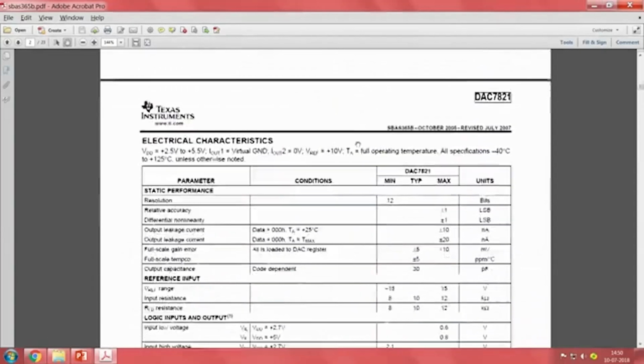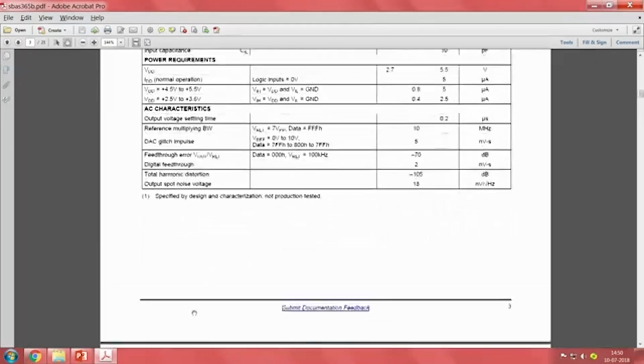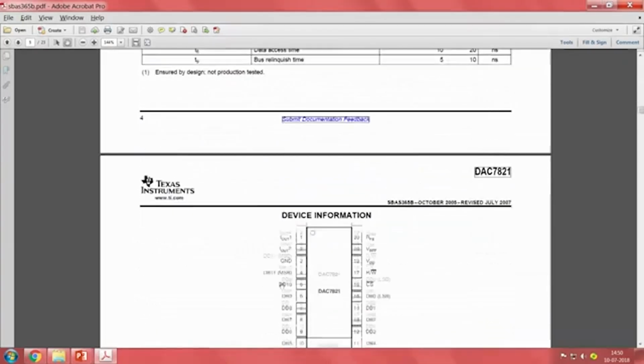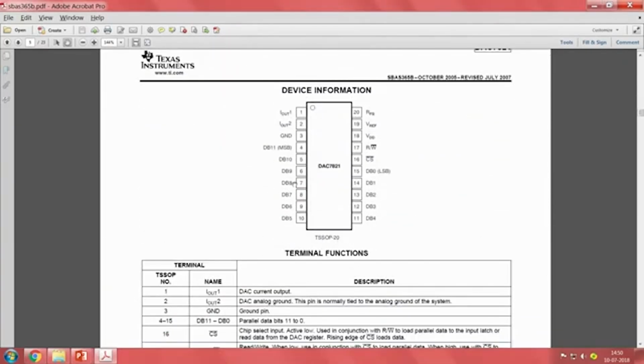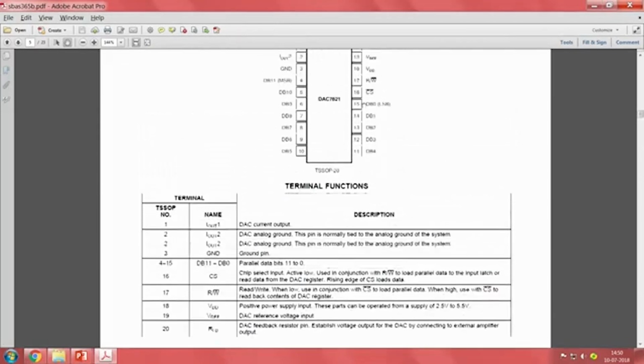Cool. Then immediately you go to these things, only look at important things like reference voltage, operating VDD and all, then that will be done. Then quickly, after that the main thing is the package and the pin out. What all pins are there, what are their functionalities, or what you should connect to what, and that is it. Then pin out will be done, correct.